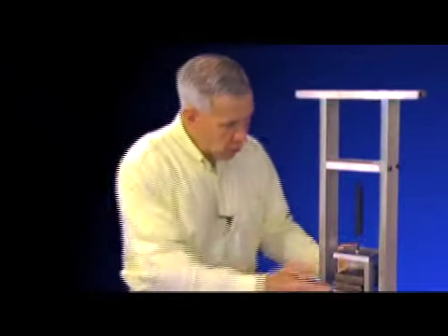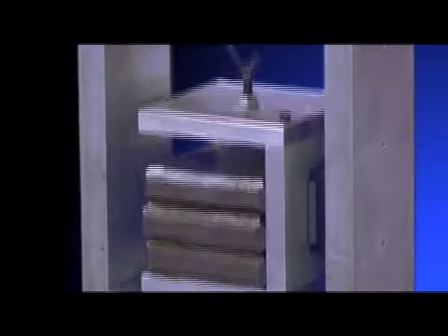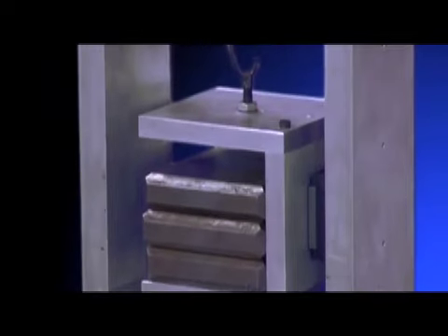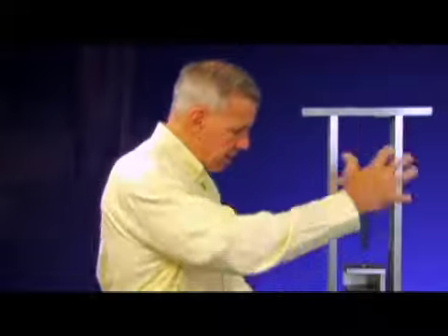But this parasitic effect, unwanted effect, is great. It's the primary reason these oscillations eventually decrease in amplitude and the motion stops. It's not because of the energy dissipation in the spring. It's not because of the effect of the air that surrounds this. It's because of the friction in that bearing. That's what dominates the energy dissipation characteristics of this system.